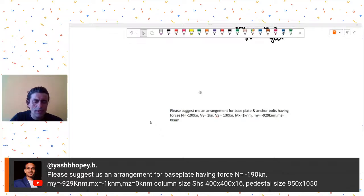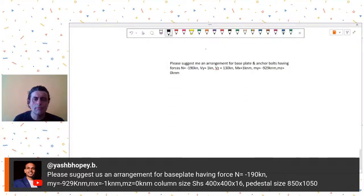Moment about one of the axis is 929. Column size is SHS 400 by 16. Pedestal size is 850 cross 1050. So what I can see is that you are getting moments only about one of the axis, and about the other axis you are not getting substantial moments.